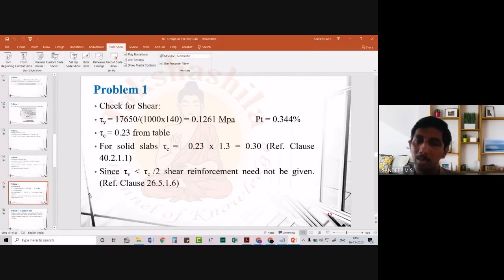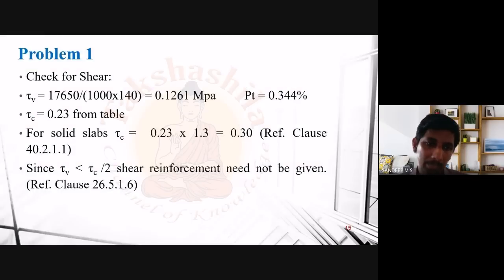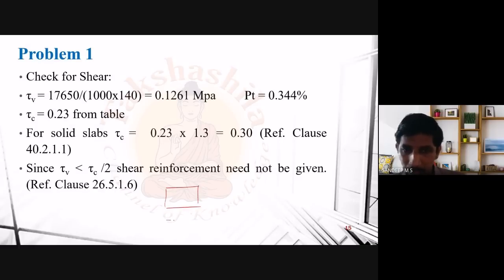We have to provide only the main reinforcement and the secondary reinforcement. So once you reach this point, you have to just provide the detailing drawing showing the reinforcements provided. That will have a plan like this. Then you will have a cross section like this here, and here also you will have a cross section to show the secondary reinforcement.